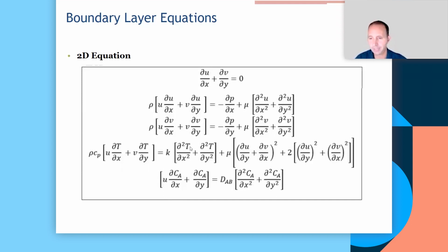So if you see the second derivative of the conserved quantity, it means you're dealing with a diffusive process. Diffusion, diffusion, diffusion. If you see the velocity linked to a gradient in the conserved property or variable, then it means we're dealing with convective transport. So convection, convection, and convection. And this is mass conservation. Okay, so that's just a very rapid review of things we would have discussed previously.